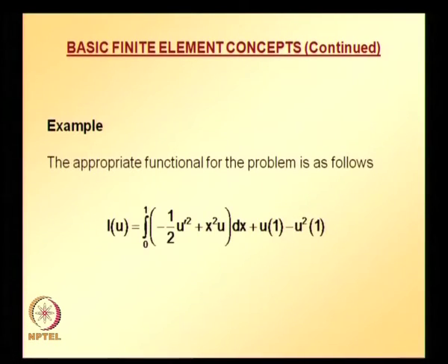And now we define what is the trial solution for this problem in terms of finite element shape functions and the nodal values. Now we are ready to solve the problem that we are looking at. The equivalent functional for the problem that we are looking at, using Galerkin method, variational method, is here.